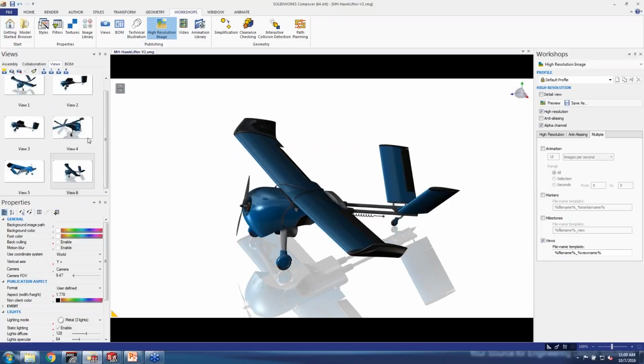Let's say you had this big piece of machinery, and you didn't want to bring the whole thing into Composer, so you would bring maybe this subassembly, that subassembly over there, and those would be all different Composer projects, different Composer SMG files. And each one of those controls a different set of images in your final documentation. So let's say that SMG number 1 controlled images 5 through 15. Number 2 controlled 16 through 32, and number 3 controlled 33 through whatever, 68.